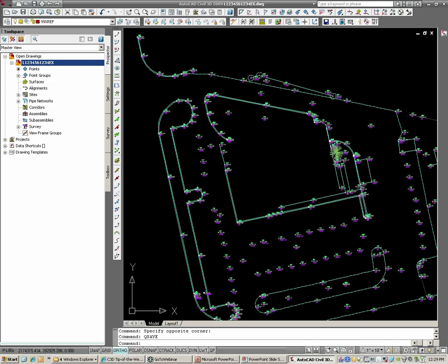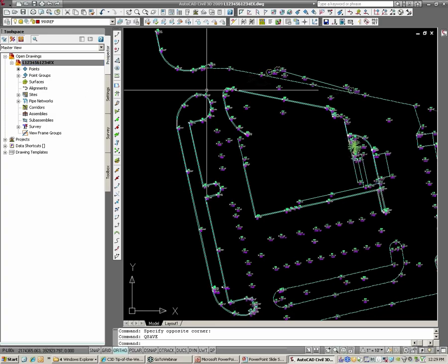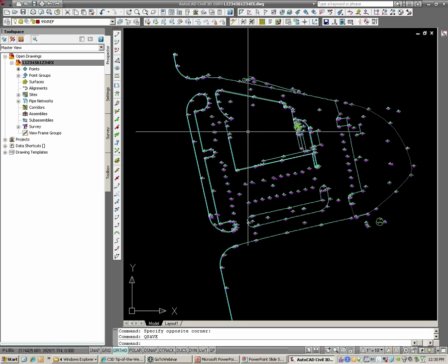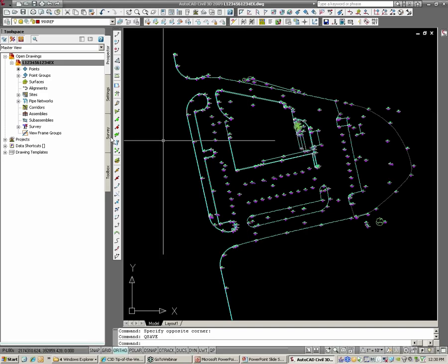Okay, I got a question here, and Chris, I do appreciate that question. That's a great question that I need to cover. Almost glossed over that. Chris asked, do I need to set the coordinate system in my drawing? And the answer that will keep you safe is yes. You do. But why didn't I do that right away? Because my DWG is set to US survey feet, and so is the survey database. So there's no conversion happening there.